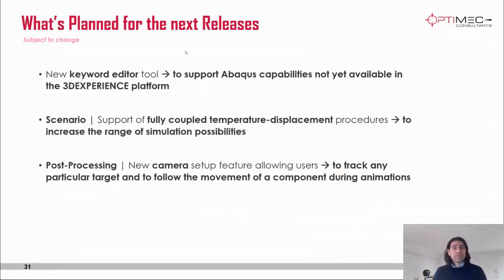On the scenario side, there's going to be support for fully coupled temperature displacement procedures, so that will give you more possibilities for simulation. And on the post-processing side, there's a new camera feature that allows you to track any particular node or part during an animation or anything. This is a nice feature to have when you present the results.